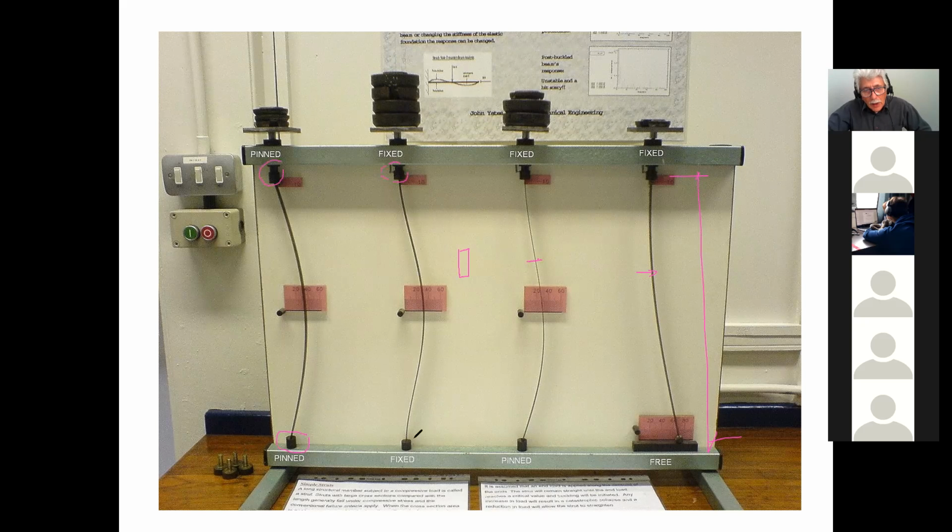What I like about this picture is that it gives you a real appreciation of, for example, when I have a fixed end, look at the load that this column can carry, as opposed to when it's fixed and free to translate. Look at that. Isn't that amazing? In other words, the K value goes to 2.0 here, and here the K value is 0.5.